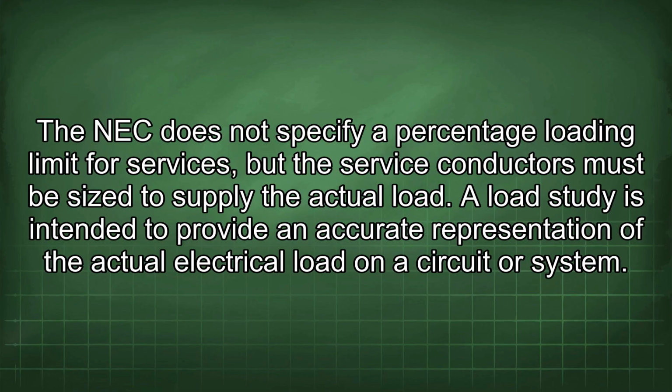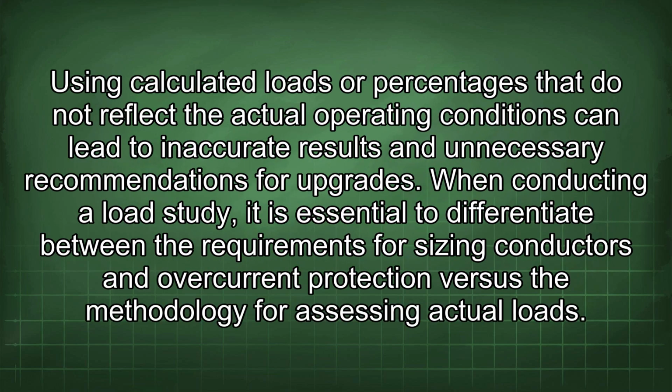The NEC does not specify a percentage loading limit for services, but the service conductors must be sized to supply the actual load. A load study is intended to provide an accurate representation of the actual electrical load on a circuit or system. Using calculated loads or percentages that do not reflect the actual operating conditions can lead to inaccurate results and unnecessary recommendations for upgrades.